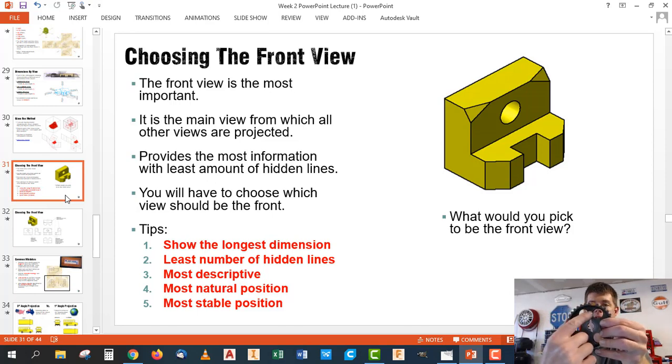You guys may not be able to see this, but there's a little pin up here at the top on this thing. So if I was going to draw this, out of all the different configurations and rotations I can do to this, I'm going to make sure that I mount it with the correct face out. That's going to become my front view because that's how it's going to be mounted on the engine. And then to try and decide what is up, I'm going to put that locating pin at the top in my drawing. So I would draw this thing like that.